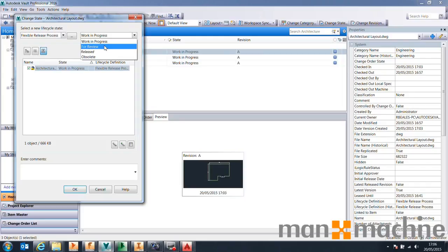And all I want to point out at this stage is with Project Sync for Autodesk Vault, we have the ability to go in and customize these life cycles to create checked out to Buzzsaw states. For example, we could have an external approval where at that point a file is synchronized directly to Buzzsaw and checked out to Buzzsaw, so it cannot be edited by anyone but the relevant Buzzsaw users.